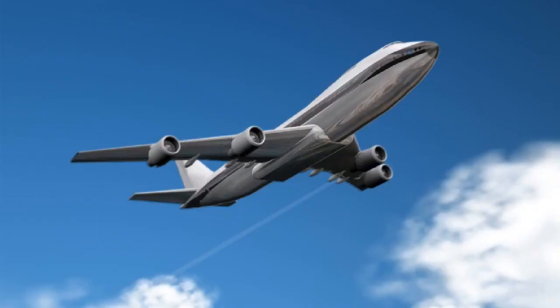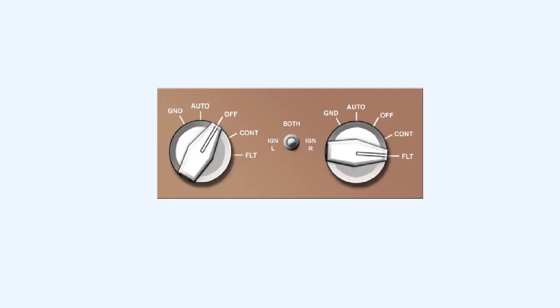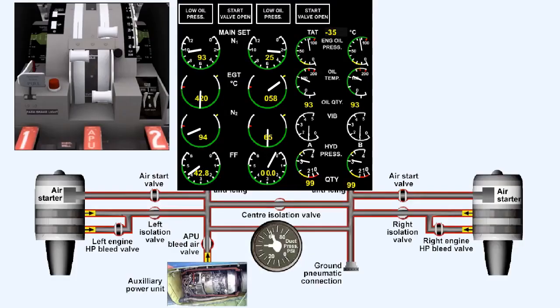In the event of an engine flaming out while the aircraft is airborne, it may only be necessary to initiate the fuel flow and activate the ignition system without operating the starter motor to achieve a relight. The starter motor should not be required to rotate the engine in these circumstances because the engine should already be windmilling. On this aircraft, if both ignition systems are selected and the appropriate engine selector moved to the flight position, a relight should be achieved if the failed engine's start lever is moved to the idle detent.